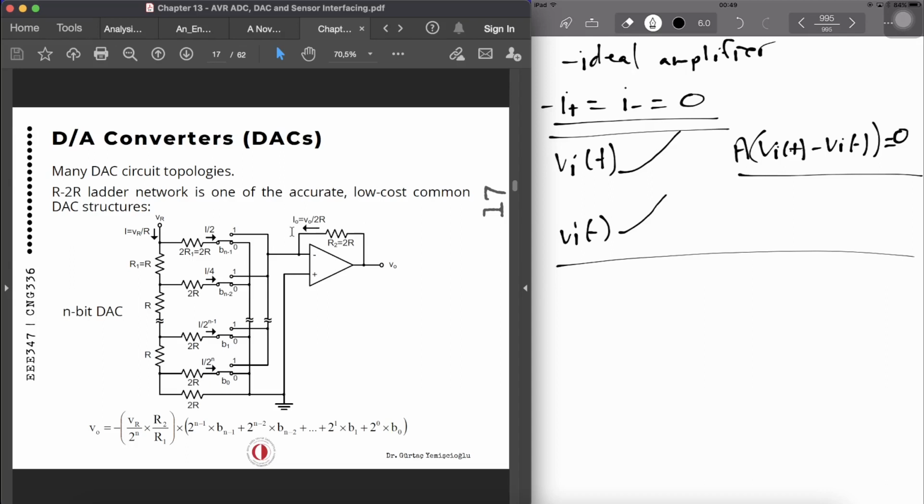And now we are going to establish another relationship for that current by doing KCL. If you do remember KCL. Now, like we have said before, the current going in one direction has to be 0, because that's the input to the amplifier. Which means whatever current comes into here has to go in the other direction as well, as long as there's any circuit for the current to flow, which is actually there.